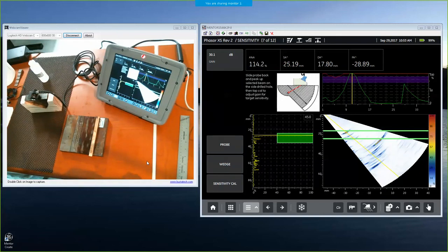The problem is if you have any variation when you go section to section, you get a very crisp line along that angle that ultimately doesn't hurt your inspection. It just makes the picture look a little worse. But that's really the only way around that. Okay. Either that or you need a physically very large block where you can separate the indications far enough that you're only seeing one indication on the whole sweep of angles at a time.